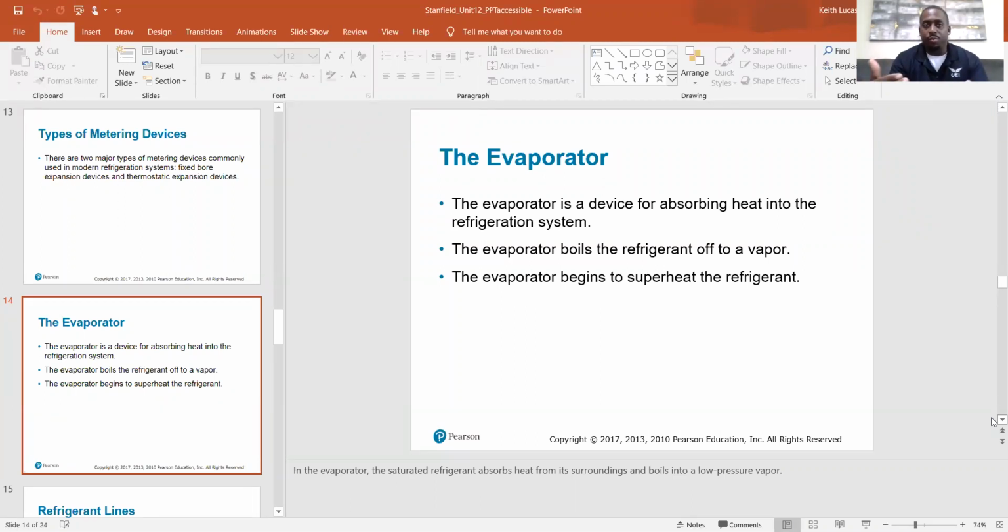So that's how we remove heat. We're not really creating cold as much as we're removing heat. So that's how we're removing heat from inside and dumping it outside. The refrigerant is doing that. That cold refrigerant in the evap coil absorbed the heat from the air that passed across it, and the air is coming out of the supply vents cold. That same refrigerant that just absorbed all that heat is shot straight out to the condenser, where the heat is then rejected right out into the air.